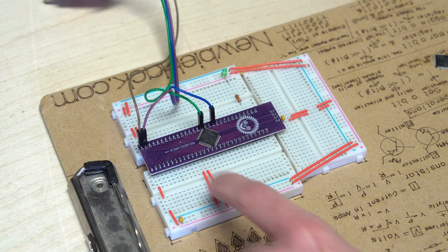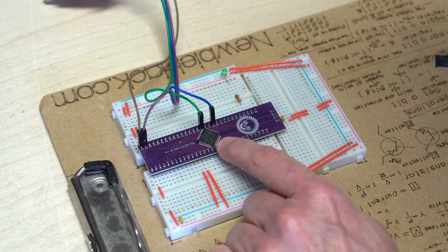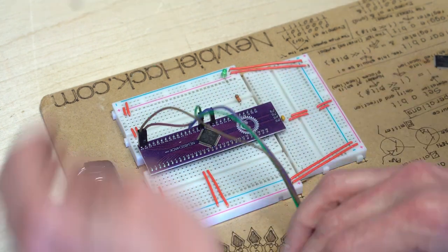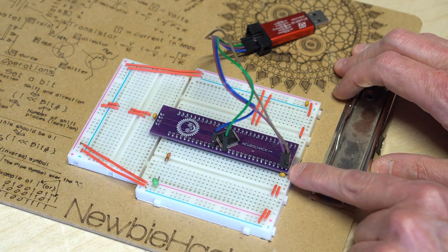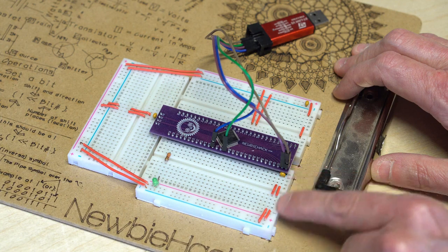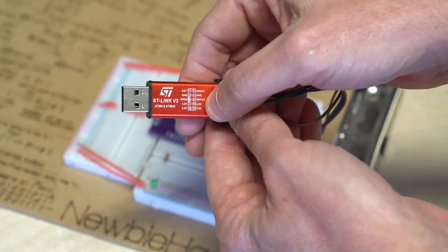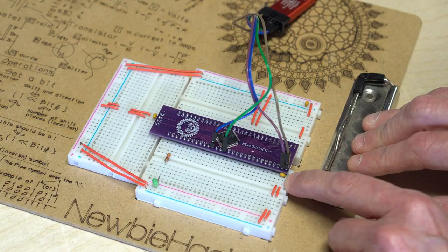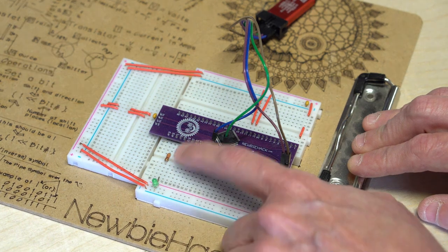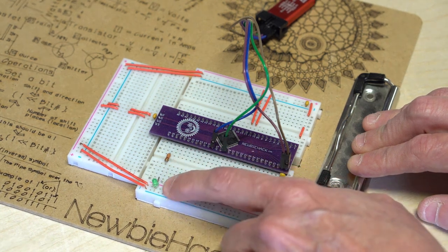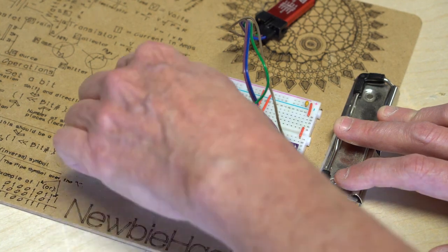The circuit you're going to need is the microcontroller on a breakout board, and the breakout board is connected to 3 breadboards. There are multiple power pins that need to be connected. The power pins are 64 and 63. Pin number 64 is connected to the positive, which is positive 3.3 volts, and pin number 63 is connected to ground, or the negative. I've connected an LED to pin number 37, but you don't need to do this for this particular project. I'm tying the breadboard power rails together using these wires here.